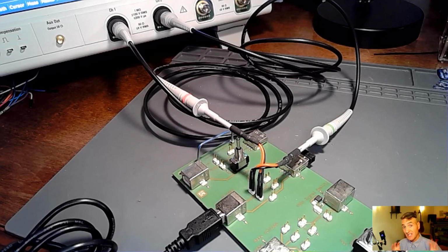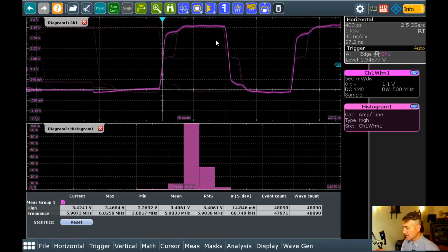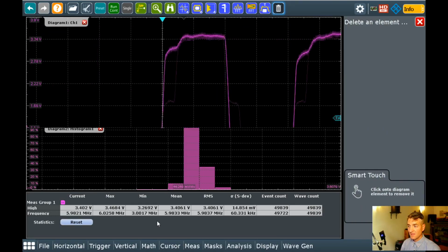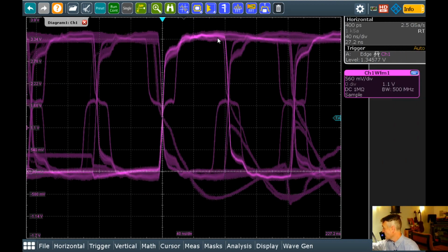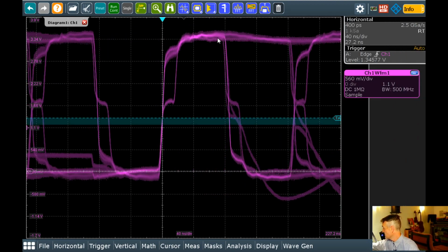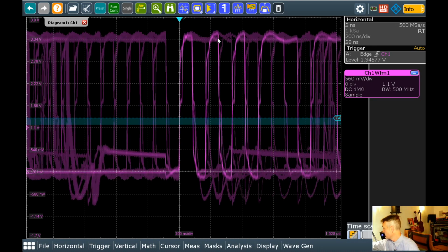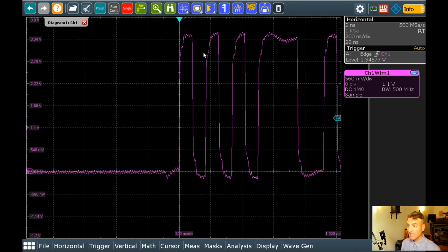We're going to start doing some decoding and some digital analysis because guess what? These signals on this oscilloscope, let's delete my measurements and get everything out of the way. Go back to just a single, let's do a single shot. So we'll single. Guess what? These pulses that are up and down, these are 1s and 0s. This is digital traffic. So this would be a 1, this would be a 0, a 1, 0, 1, 0, 1, 1, 0, 0. Actually, 1, 1, 1, 0, 0.